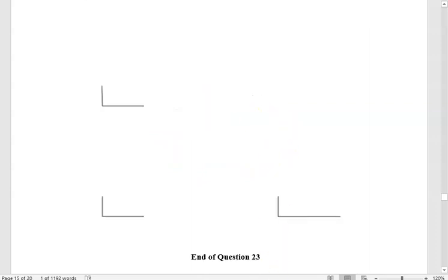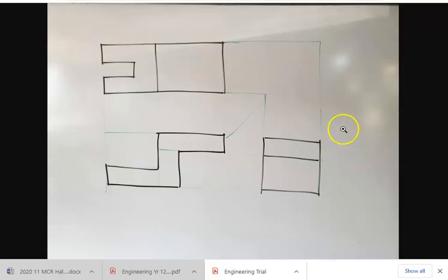Okay, so I've drawn that up pretty hastily, but I would still give this 3 marks. Even though it's been drawn freehand, it's dimensionally close enough. I did have one student who lost a mark because this line, the line that I'm showing here, was actually drawn there, and that's far enough off that I can take a mark off. If you drew the line down the bottom here, that would be the wrong side, so having an extra line there would lose you a mark.